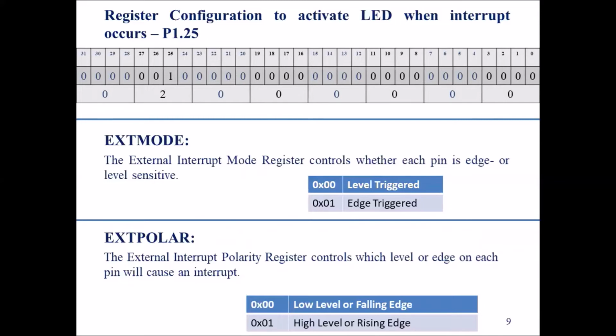We'll be using a push button mechanism to trigger the interrupt, or basically to execute the interrupt on the ongoing process of the microcontroller. When you push the button and release it, the light will glow on the LED. Again, when you push the button and release it, the light will go off. That's the interrupt mechanism in the fourth program.